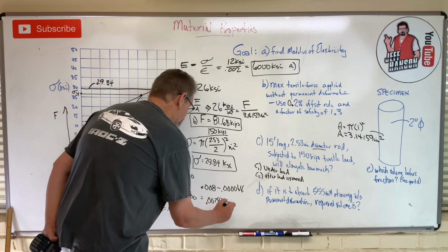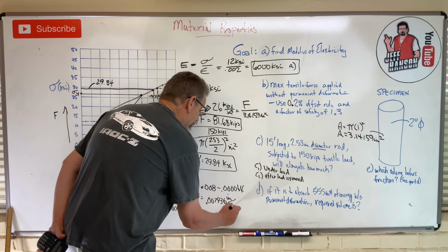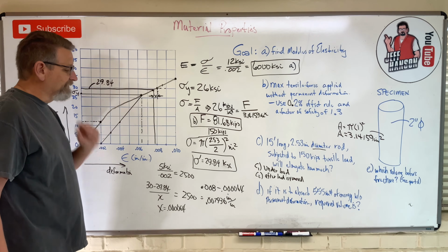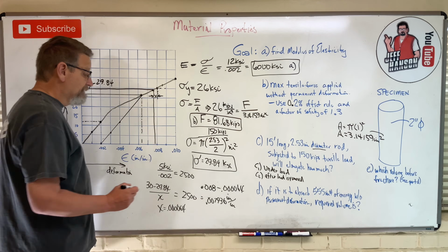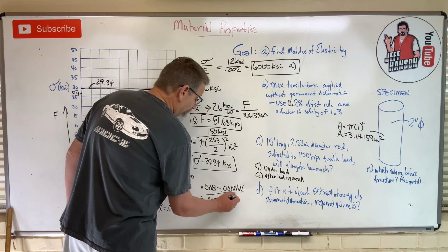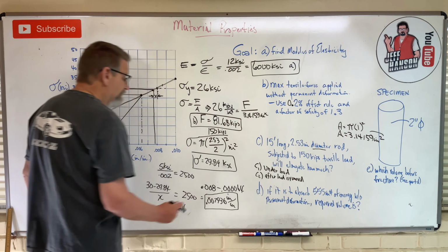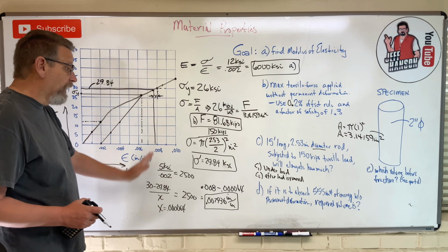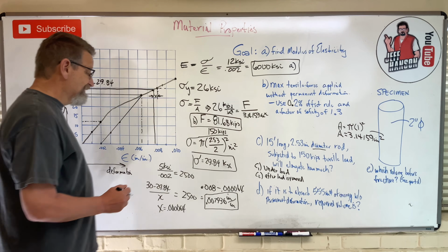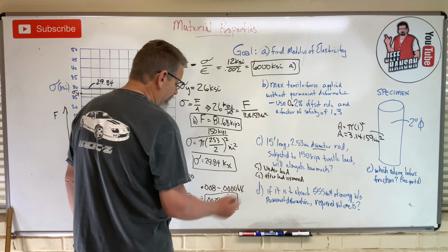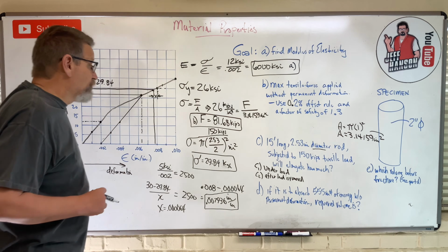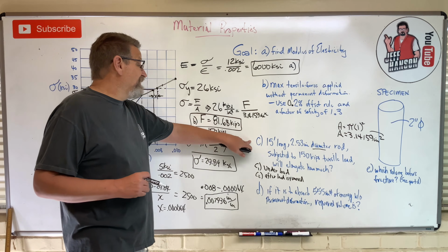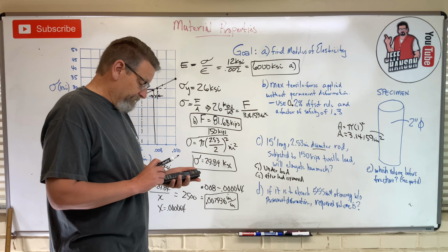And what is that? That's inches per inch, okay? Now there's about 100 ways to do that, right? It's just a linear interpolation there, okay? So that right there is the strain on that piece. Now, I could read that if I'm under load, that's what the strain is. That's in inches per inch, right? So how can I calculate the total strain on that? Well, the thing was how long? It's 15 feet long. That's a long piece, isn't it?